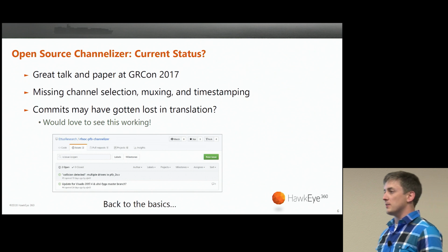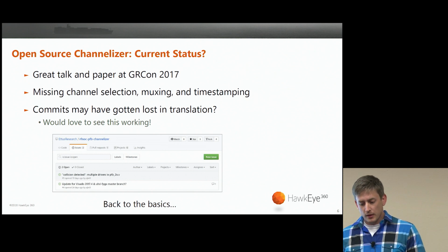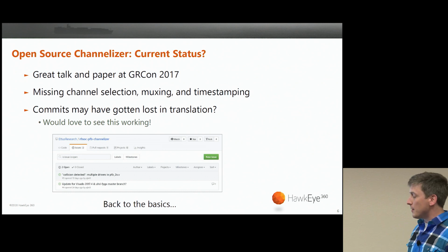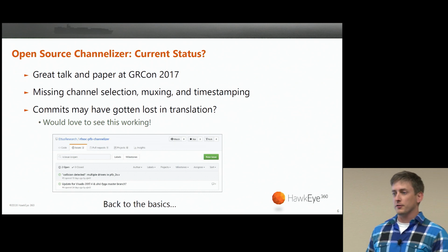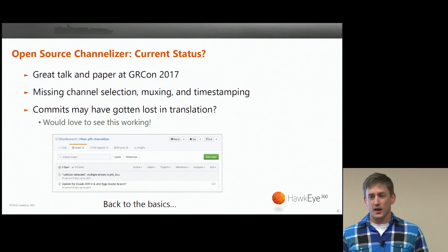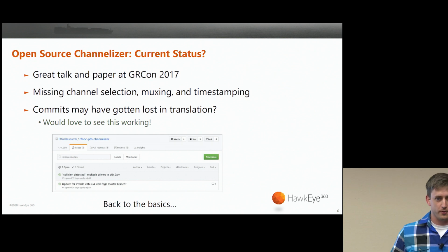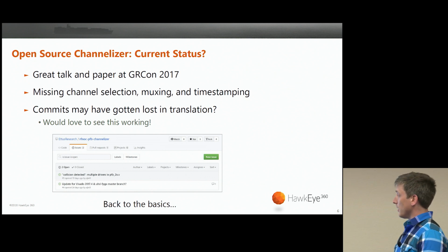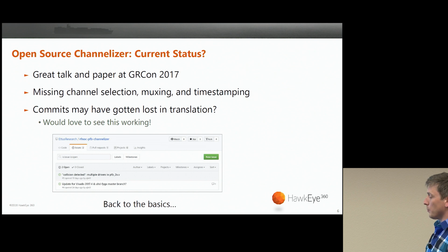And the second part of this is timestamping. So, there's a channelizer in GNU Radio. I want to be able to handle timestamping in the RFNoC framework so that you can take timestamps in the FPGA and move them around and do useful things with them. That's really important to us. As you can imagine, we're doing physical measurements, T2A, F2A, so the timing component and propagating that timing is critical.